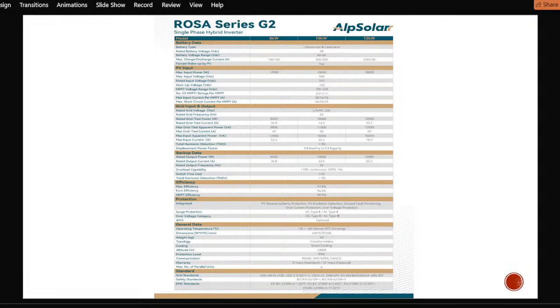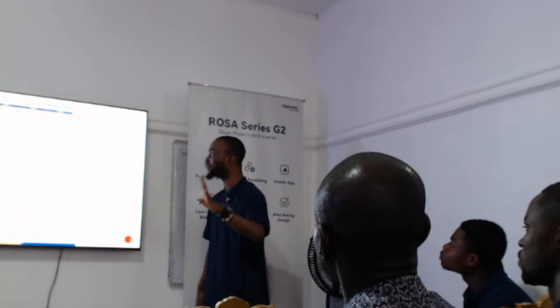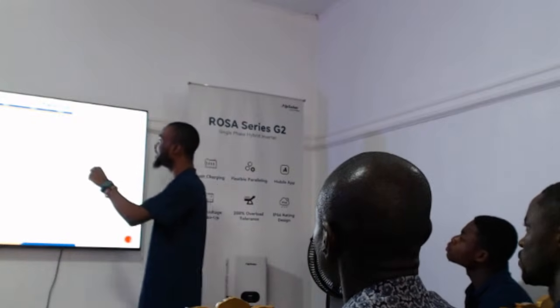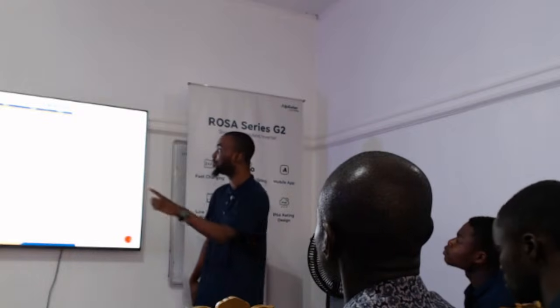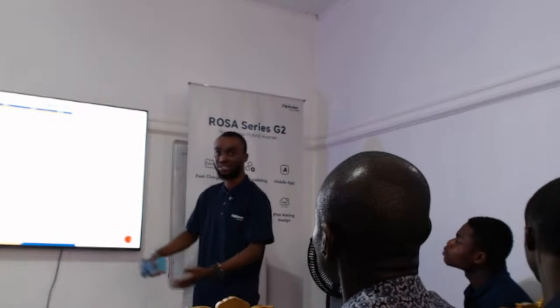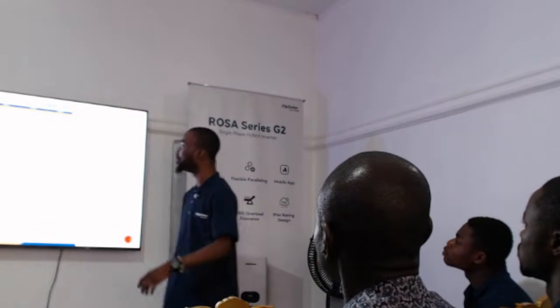So it gives opportunity to just put all of your connections in series up there. And you will agree with me that series connection is quite easier than parallel when you're doing PV. Absolutely. And it's even suitable for high installation because you don't need more current. You are not paralleling together, you are not building up current, you are building up voltage. So your current is preserved. So it's okay for you to series all of your connections and bring down 4 ports coming from there. Then the maximum short circuit current per MPPT: though the rated is 28, the first can take 45, and the remaining MPPT can take 25 amps each.